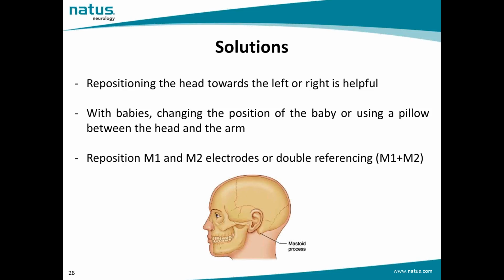In addition, touching the electrode producing the artifact can help to identify it by both confirming the movement of the electrode with the pulse and altering the artifact's appearance on EEG as pressure is applied. Contrary to ECG artifacts, pulse artifacts can be eliminated by reapplication of the electrode at some distance from the pulsating artery. To reduce the probability of ECG artifacts, care should be taken to avoid placing referencing electrodes M1 and M2